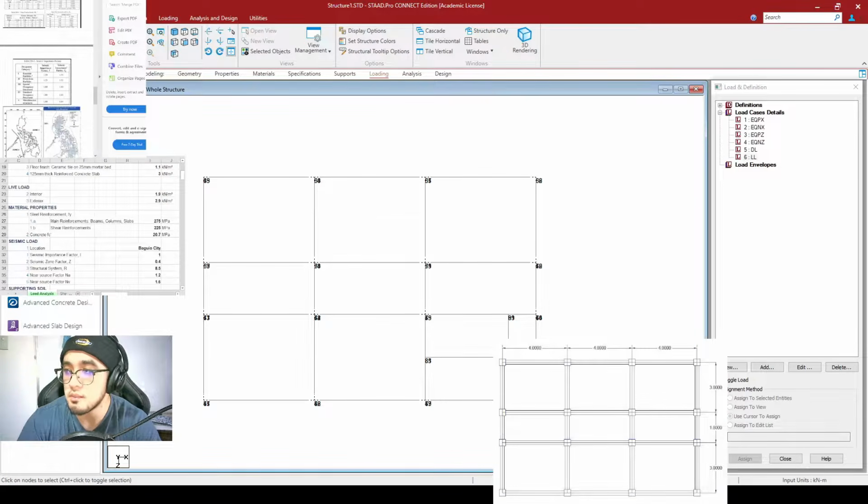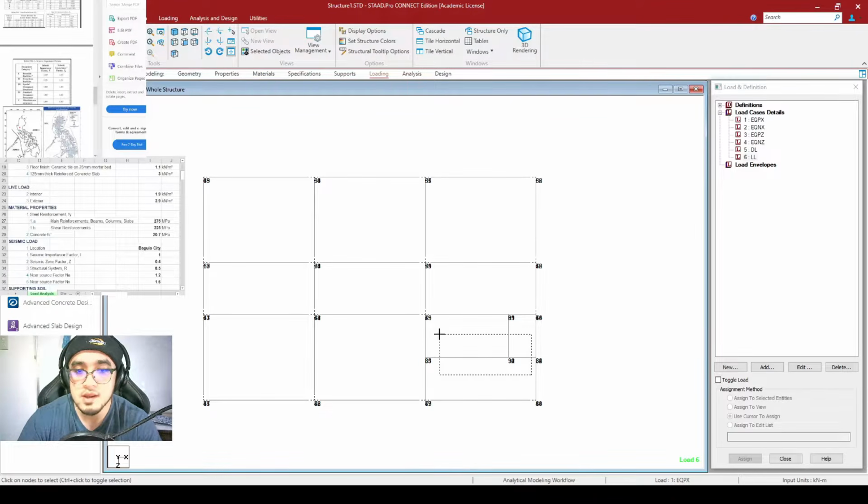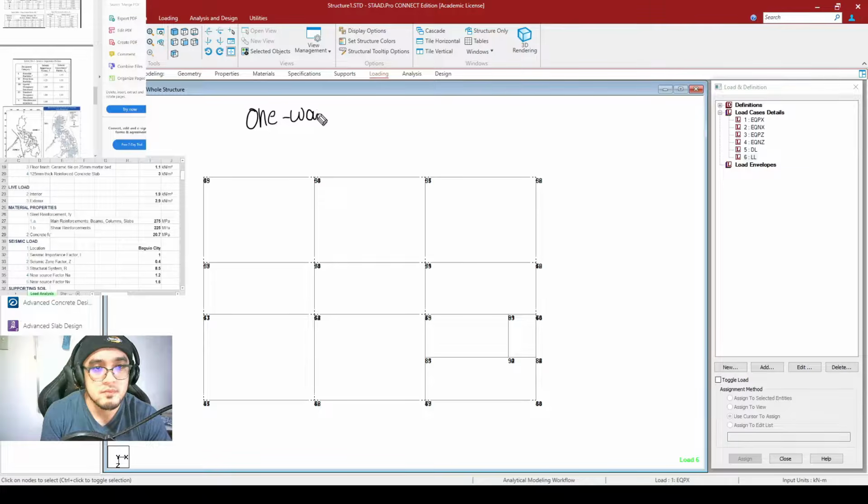So this is to be our plan at your lower right part of the screen, except that we now have these additional intermediate beams right here. Okay, so if you can remember from your reinforced concrete design that your slabs is to be categorized into two. So the first one is what we would be calling your one-way slab and the second one is what we would be calling your two-way slab. One-way and two-way slab. And they are to be given by these limits.